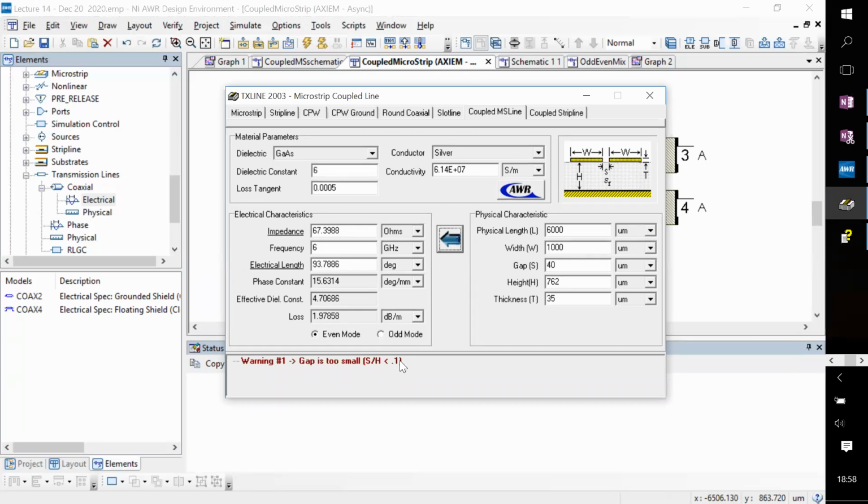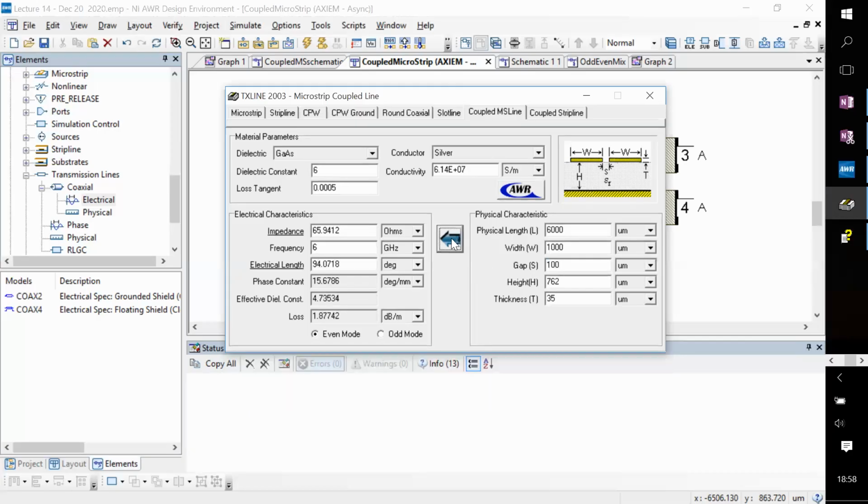In fact, you see, there are some things where you cannot make the gaps very small. But for a microstrip, I think you cannot make these very different from these values here. But for strip lines, you can. And that doesn't matter. They don't have to be 50 ohms, because most of the time they're used when some kind of interference effect is being exploited. So I will actually tell you which parts to read, which explains the device performance.